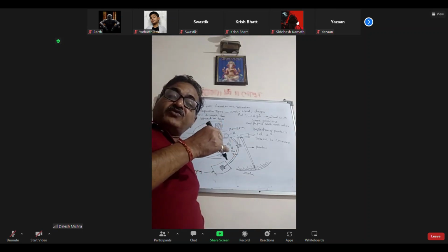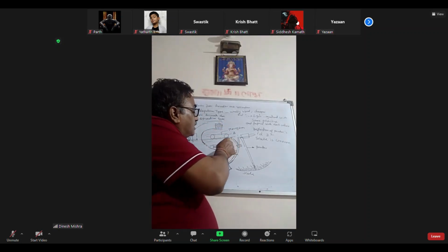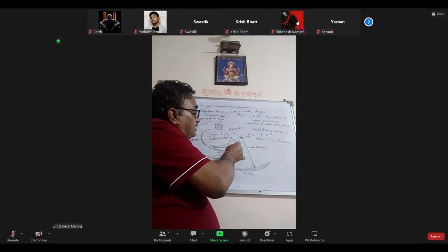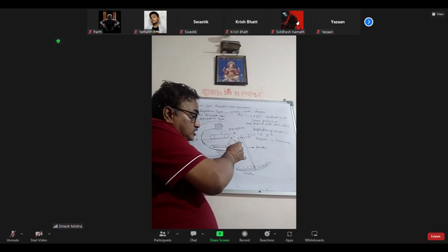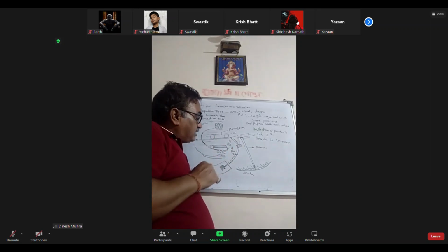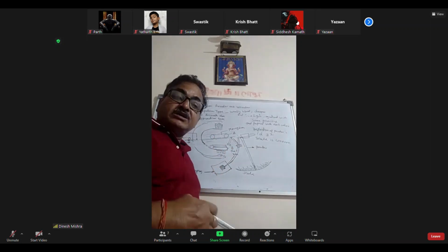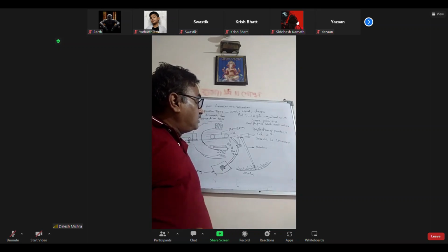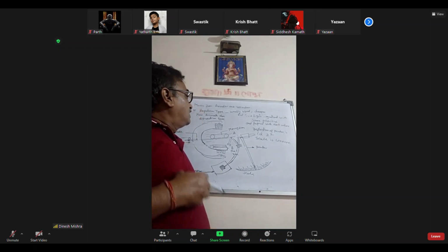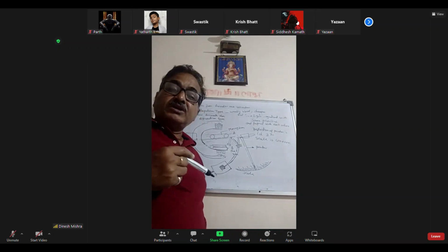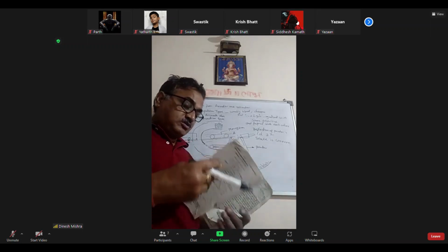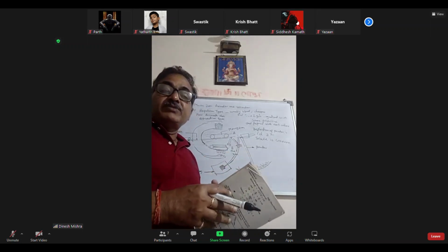The deflecting force is controlled by gravity weight. The controlling system is given by gravity control, and the damping system is given by air friction damping. Understand? This is more accurate, widely used, cheaper. This is all about the repulsion type instrument.